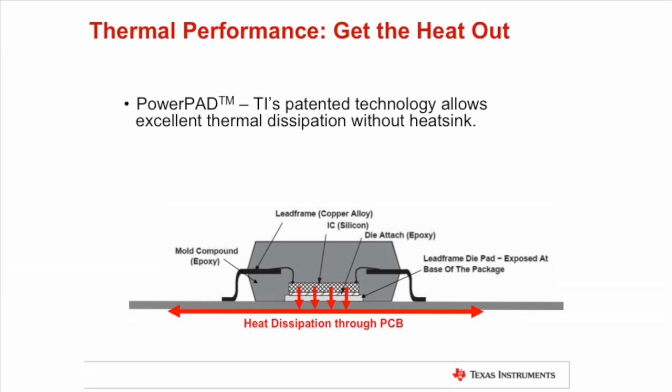So that means if you don't have good layout in terms of thermal, right? If you don't have adequate copper, the right percentage of copper in the planes, you're not going to get as good a thermal performance. So it's very critical that you make sure from a thermal perspective that your layout can handle that heat. The other characteristics of that package are the package itself.